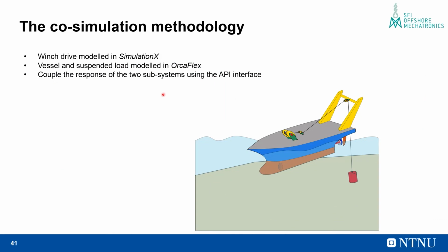So in the Cosimulation methodology, we model, for example, the electrohydraulic drive of the winch in a Modelica software called Simulation X, while the vessel and the suspended load is modeled in Orcaflex, and then we use an API interface to connect both these subsystems.